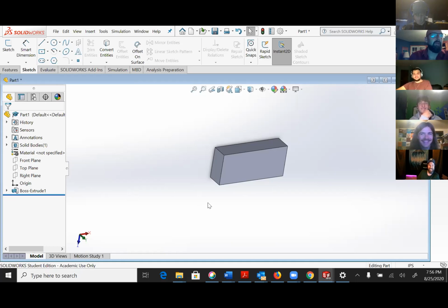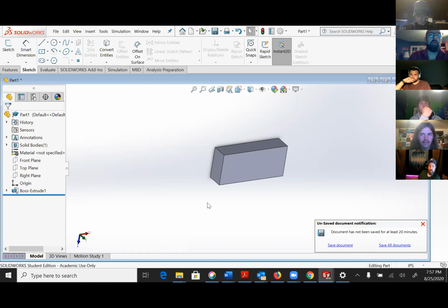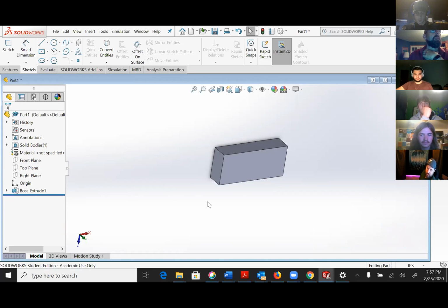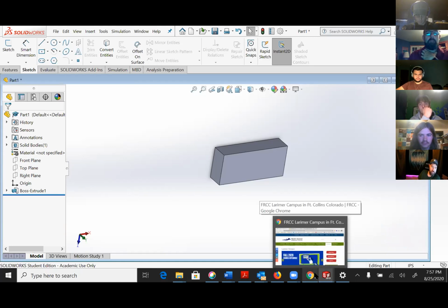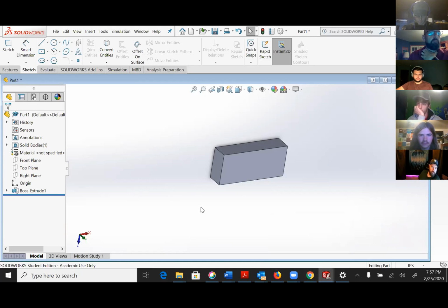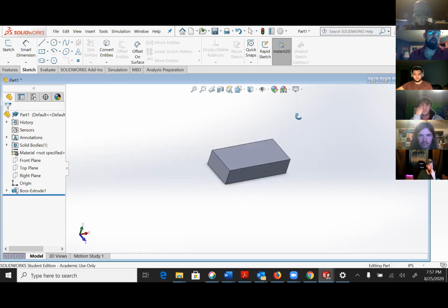How do you specify which direction to do your dimensioning? Because I'm trying to do it and it only wants to do it on a single plane. And I'm like, no, I want you to go this way. I'm not exactly sure what you're saying there, Jeff. Well, if you look at your clamp block, I'm attempting to recreate that, and I'm trying to do the dimensions, only my 6 is going in the Y direction instead of X direction. So I think what you're saying is I just make the clamp block from this sketch here. You may be trying to do too much in one sketch.